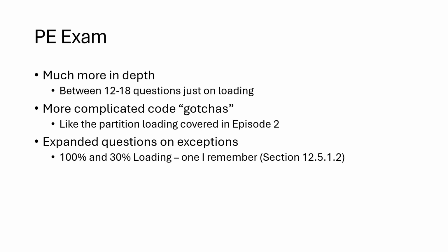An example of this is the 100% and 30% orthogonal loading. I specifically remember this question from either, I don't think it was actually on the exam, but it was during the preparation. This is in section 12.5.1.2 of ASCE 7. And again, this is determined based on the seismic design classification, or the seismic design category.